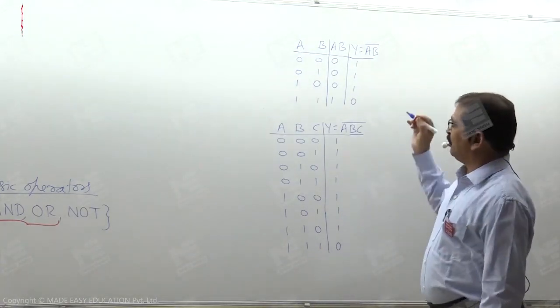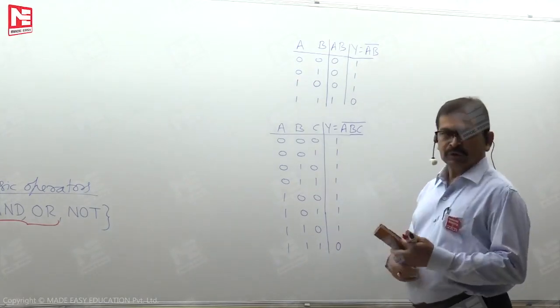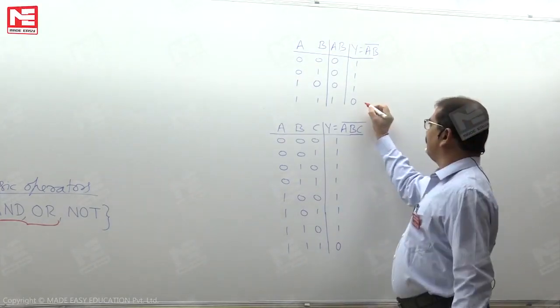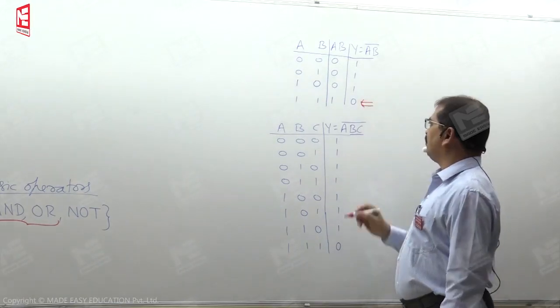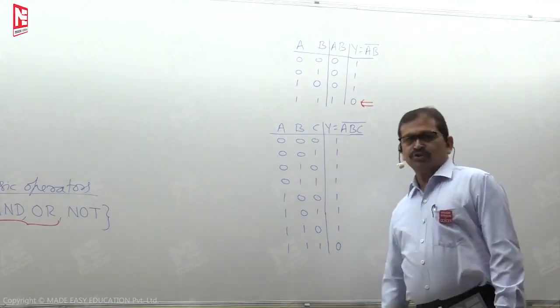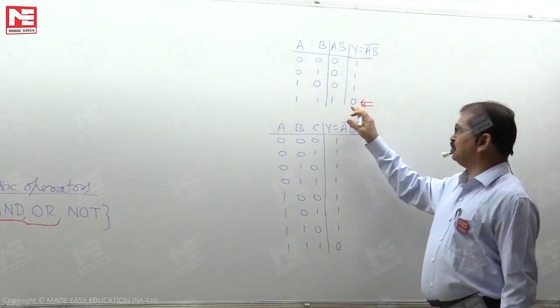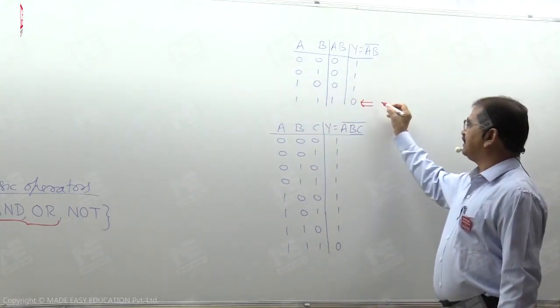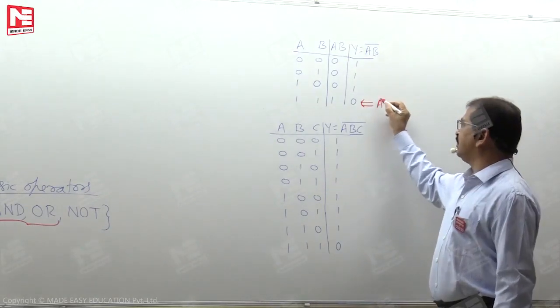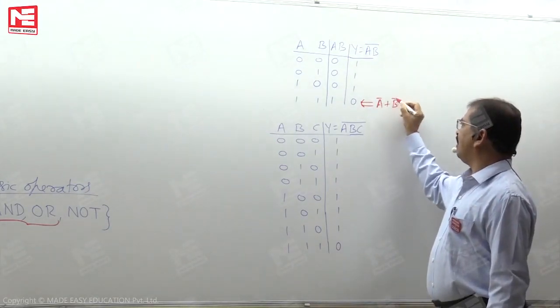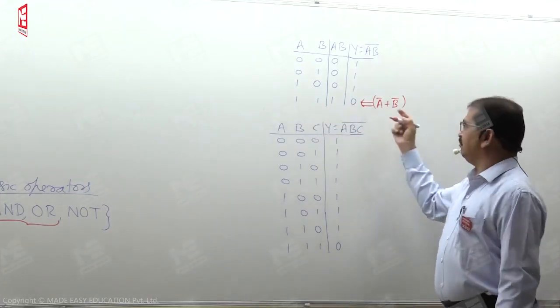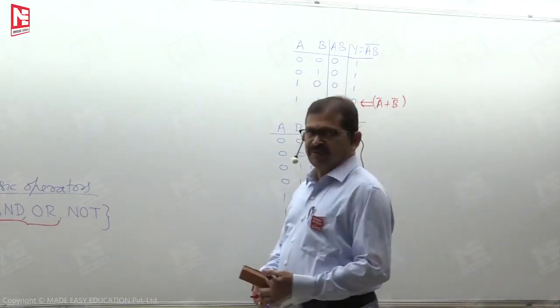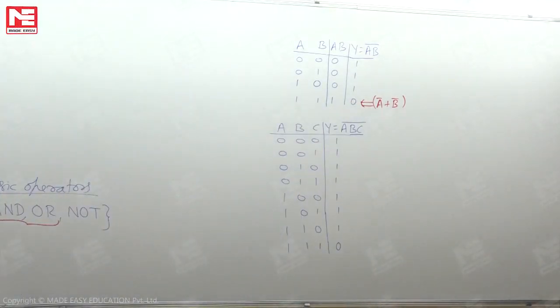From this two variable truth table, suppose we look at the POS form for this NAND operation. To read the POS form from the truth table, we refer to the combinations where the function output is 0. There is only one such combination. Because A is 1 and B is 1, the term is A complement or B complement.